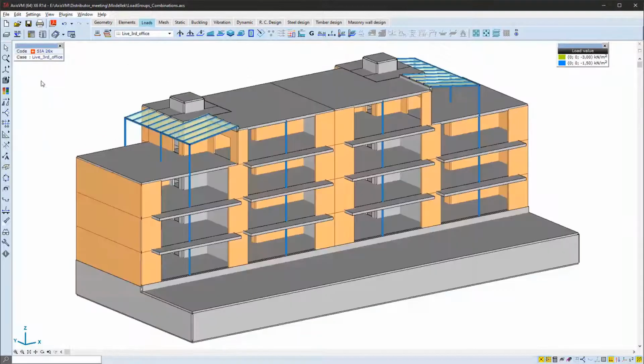If we would leave the critical combination generation for the program, we would probably end up with several, maybe thousands of load combinations, which is often not ideal. It takes a lot of calculating power from the machine, and it would also not be able to handle the 2 top stories where the function can either be office or residential area.